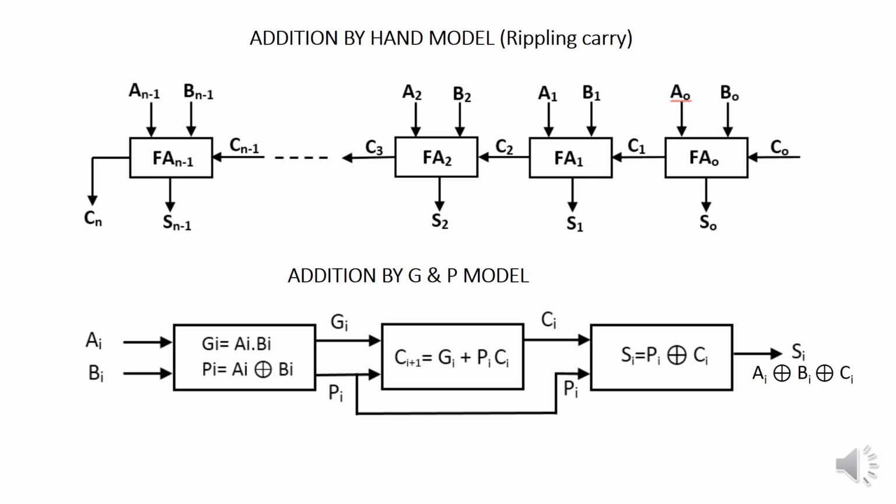To see the importance in practice of these functions we have just defined, let's first draw the circuit for the summation using a concatenated chain of full adders in a similar way as we normally do by hand when we make an addition. Technically, this is called the ripple carry adder.